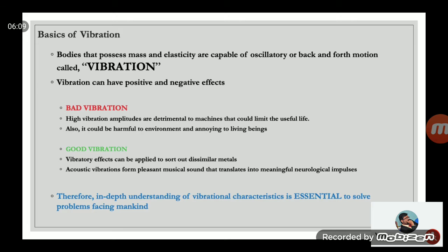High vibration amplitudes are detrimental to machines, because if you reach the highest vibration level, then it will reduce the useful life, because the fatigue life is expended already. If you originally designed for, say, 30 years, then it may not last 30 years. So it's very important that you reduce the high vibration amplitudes.